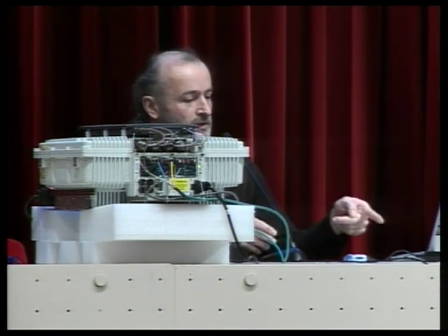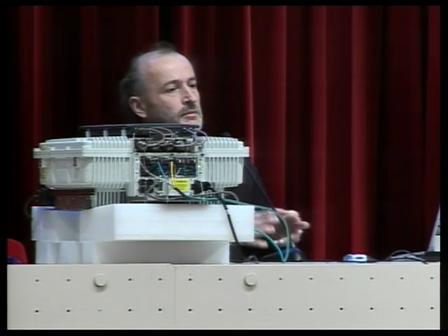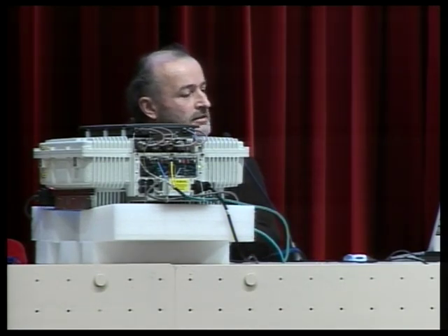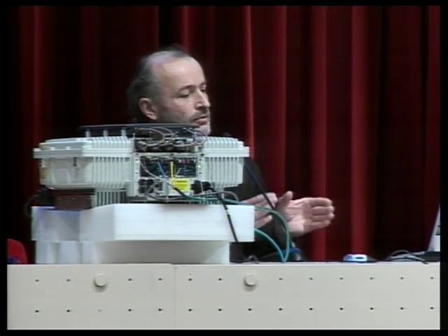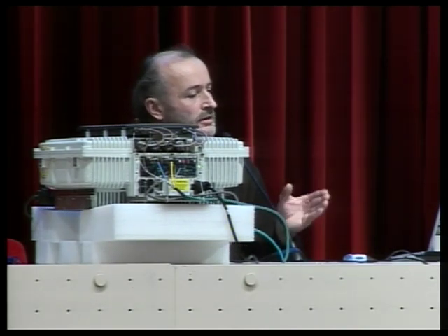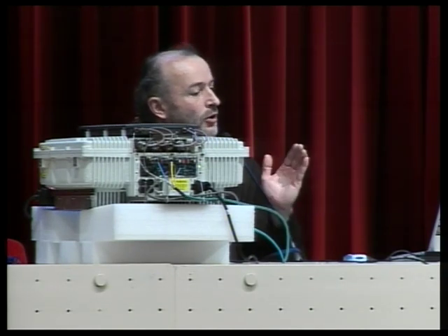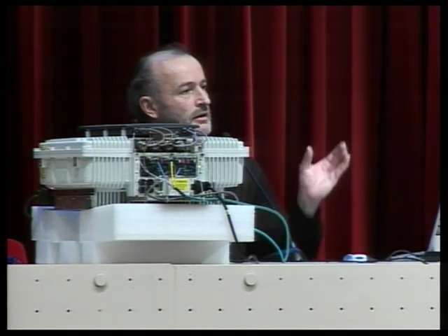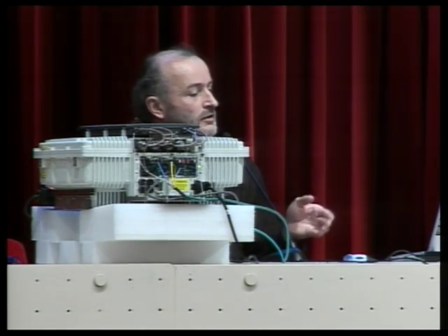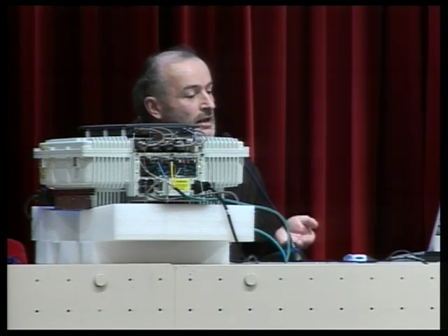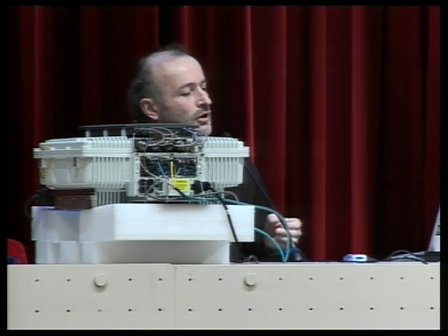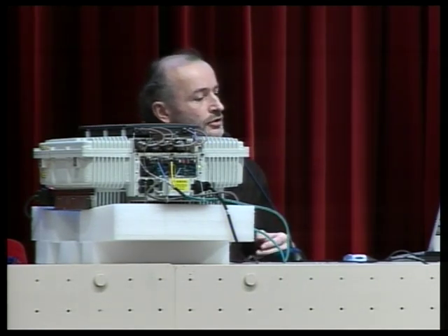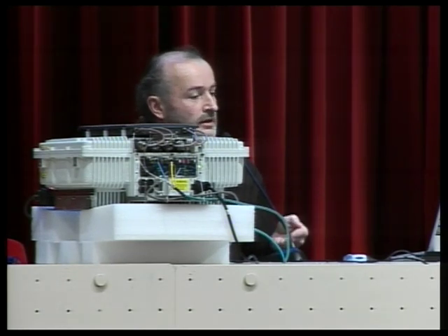You don't see speech starting or speech ending. You have this data stream and you look in it for where the package starts and where the package ends. And then you have this package, which in GSM is encoded and holds 20 milliseconds of speech. This 20 milliseconds of speech is repeated with 50 hertz frequency, so you get a continuous stream of single packages of compressed speech. In GSM, speech is compressed using several codecs.